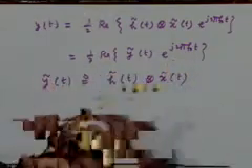So I totally can avoid working with bandpass signals, even though my basic interest is in working with bandpass signals. Right? And the advantages that accrue are that I don't have to write those lengthy trigonometric expressions which will always be there in the bandpass signal representation, because it is x r t cosine 2 pi f naught t, x i t sine 2 pi f naught t, etc. Or even in the complex representation, I keep on carrying that e to the power j2 pi f naught t, e to the power j2 pi f naught lambda, t minus lambda. Those terms are not necessary to carry with us.